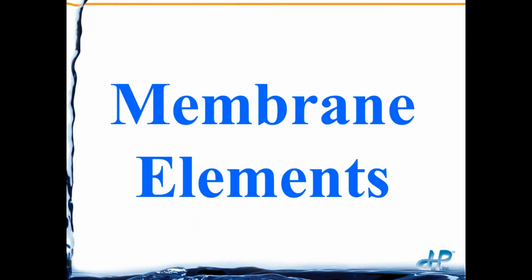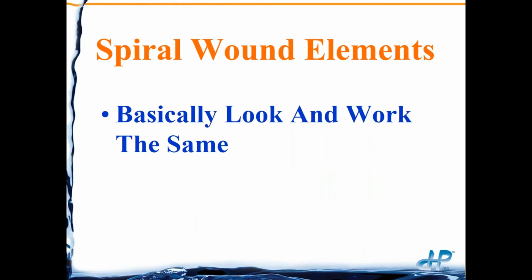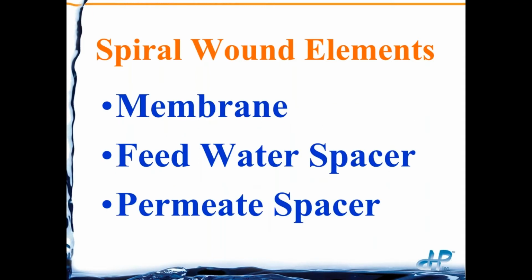So starting off this first section here, we want to make sure everybody's on the same page. So I do have a little bit of basic information on membrane elements so that you can know what we're talking about on these membrane elements, what's inside of them. Of course there's several manufacturers of membrane elements. These basically look and work the same. They're basically interchangeable from one manufacturer to the other. The only thing you have to change inside the pressure vessels is the elements themselves, but also the end cap adapters and interconnectors.